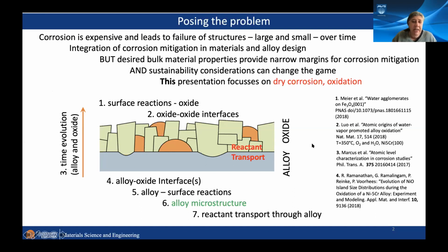But you have an oxide, which can have different oxides, which can have layered oxides. They're interlinked. You can have dual scales. So there are a lot of thermodynamically driven and kinetically driven reaction pathways, which can lead to really, really complex structures compositionally as well as crystallographically in the oxide.